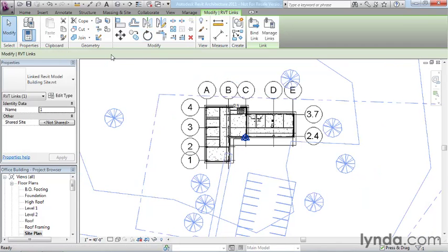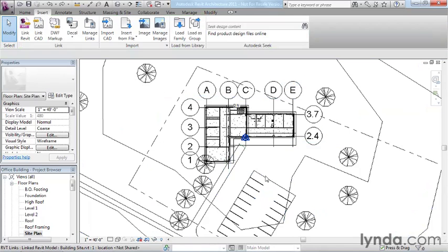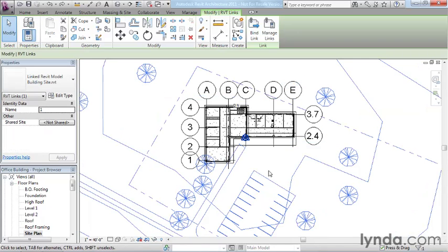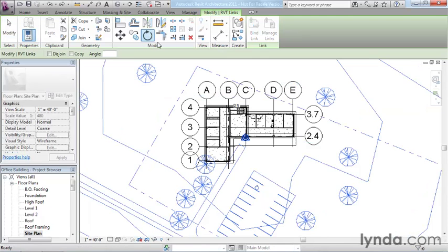But of course, it rotates around that little rotation symbol, so that probably wasn't the best choice in this case, so I'm going to undo that. What I want to do instead is select the file, click on Rotate again, and you can actually click on this little symbol and drag it. Now don't let go. If you let go, you're just moving it to wherever you let go. So you want to click and drag in all one motion, and then notice it will even object snap. So we're going to object snap to the end of the green line and then let go.